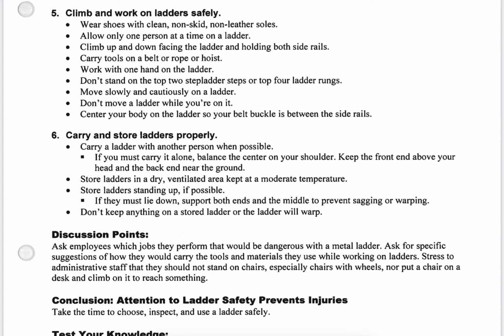Number 6, carry and store ladders properly. Carry a ladder with another person when possible. If you must carry it alone, balance the center on your shoulder. Keep the front end above your head and the back end near the ground.